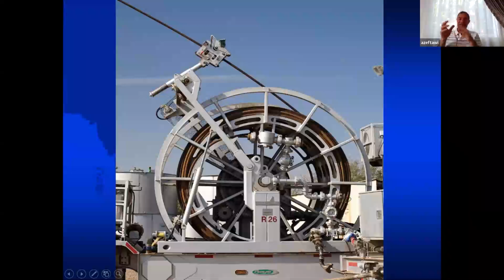So we need a crossover between what is stationary and what is rotating. So this is the swivel, where inside it has a rotating shaft, but the body itself is fixed. And since we have a rotating part inside, you have to have a packing system, a seal.